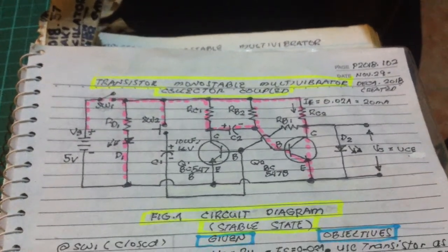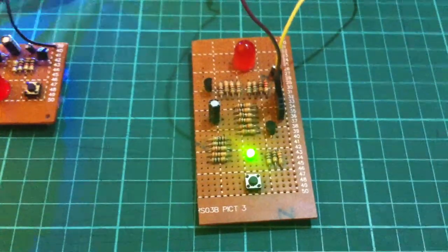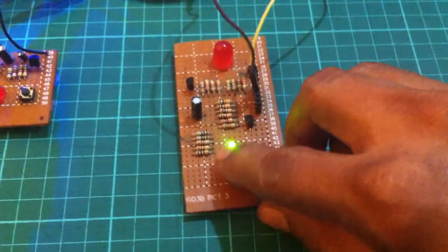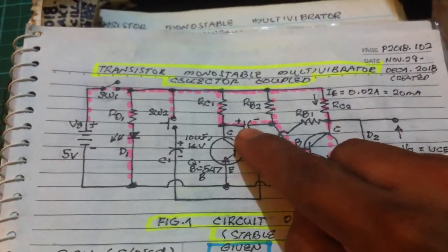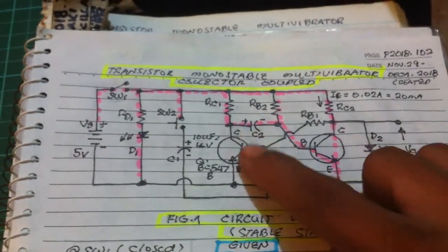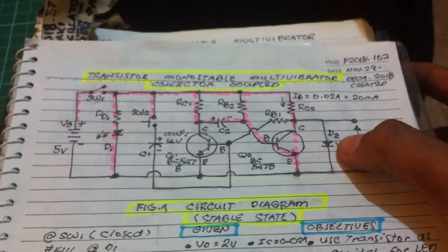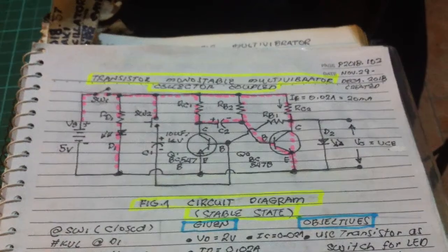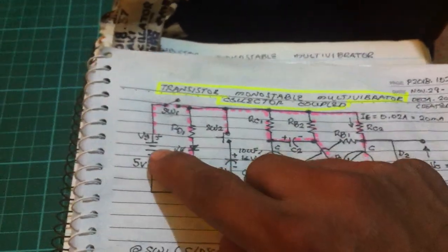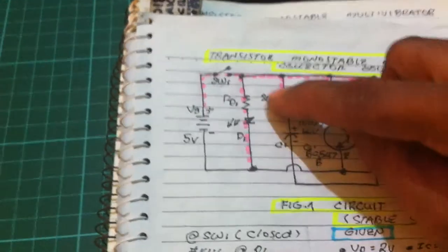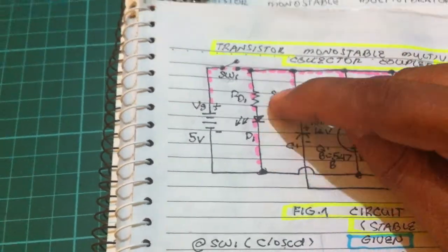Let us examine the circuit diagram of our new circuit. Pushing the button here, this is because of the effect of the capacitor connected here. That is the one controlling the light, the LED, in the output side of the circuit. So we have the 5V supply connected. This is the switch, and then the resistor and the LED. This is an LED power on indicator.